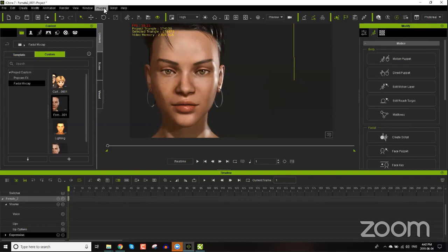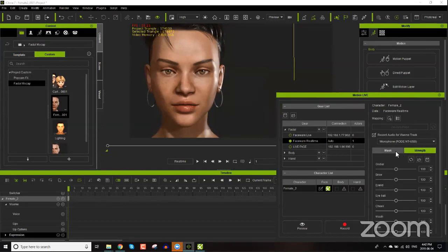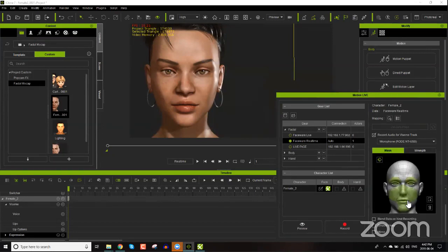Because not all of us are the best voice actors, and God knows I certainly don't sound like this woman looks. So let's go to plugins one more time, okay? So we'll go to FaceWare again, FaceWare real time. And what I'm going to do now is down here in the bottom, we have the masking, okay? So what I'm going to do is I'm going to click the face and the chin, and we're going to mask out my mouth and my chin here, okay?